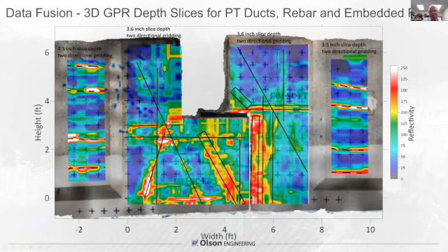So in this side view, we've identified, and it's complex, some stirrups that are in there at angles. There's vertical bars and some bars coming back this way. Plus there are embedded metal plates that are all inside the ducts. And you can see these outlines are drawn to show the features and the interpretation. Here's some horizontal rebar. And because of all this other steel, we weren't exactly, you can sort of see the extension of the duct right here. You can see the extension of the duct is coinciding in this general area here. And then the anchorages are over here for the ducts.